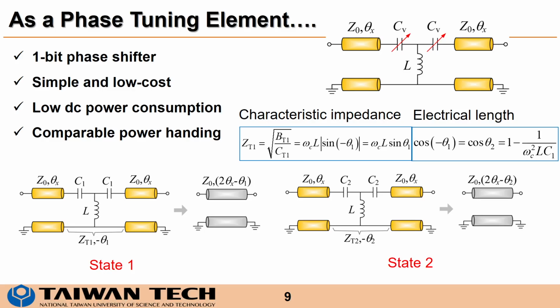However, after some manipulation, we derive that this synthesized transmission line can provide phase tuning capability without altering its characteristic impedance. Our experiments also point out that several stages of different electrical length can be achieved using this structure.